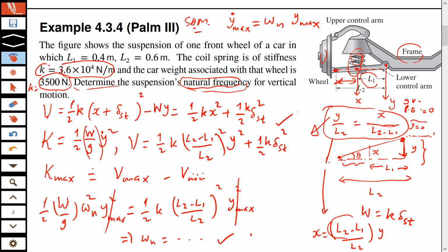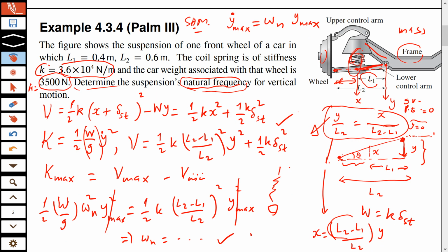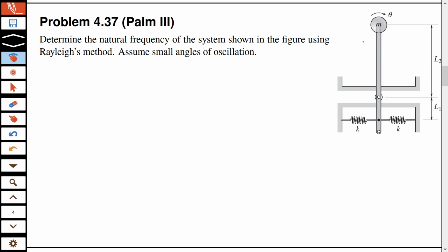One thing is important, that in both these questions, the mass, the rigid body, and the spring, although they are not on top of each other like that, are connected by rigid links. It's more visible here. This rigid link, which is massless, is connecting M and K, which means the gravitational force mg, which we call W here, will have an impact on K, and that's why we have to include this static deflection. You cannot say that this M is here. If we remove this connection, and M and the spring move independently, without a connection, then we will have to ignore this term, because that deflection cannot be there. But now we know that any motion of M will have an impact on K in both these examples. So they don't have to be on top of each other. The gravity can affect the mass-spring through any rigid link.